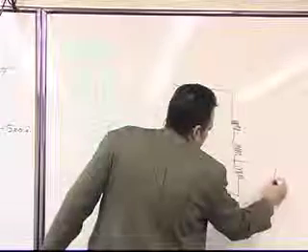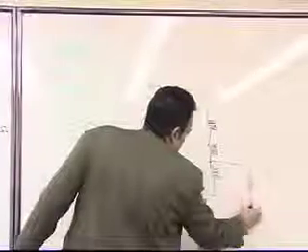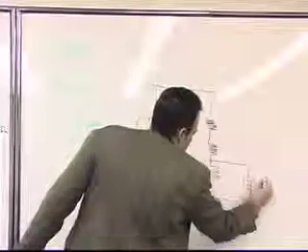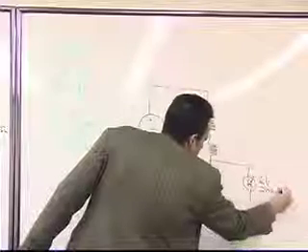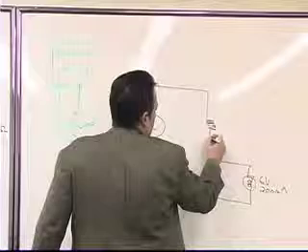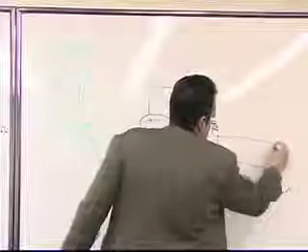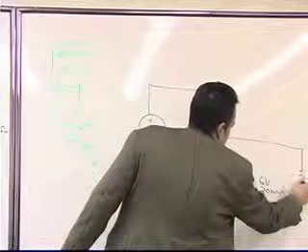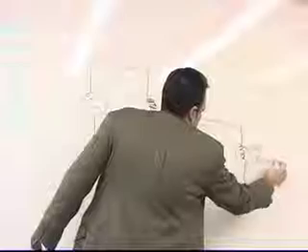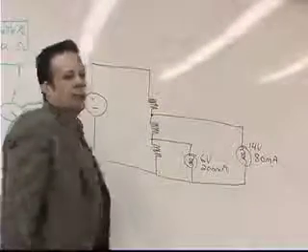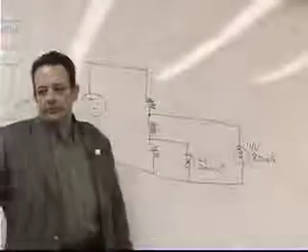Our loaded voltage divider had one light bulb in the bottom, and if you recall, it was rated for 6 volts and 200 milliamps. And then up here, we had another light bulb, and it was rated for 14 volts at 80 milliamps. Okay? The temptation is this.